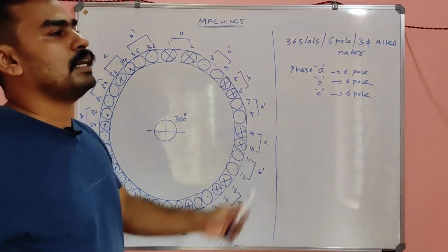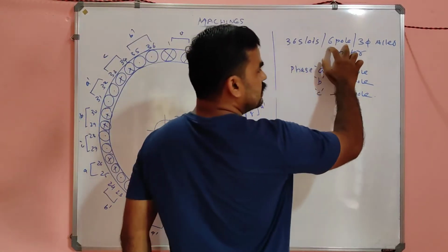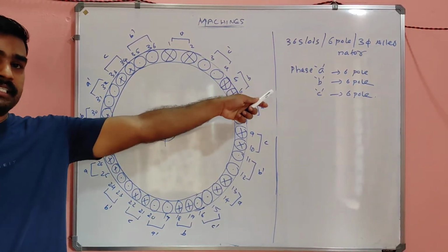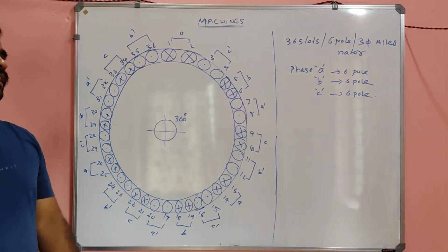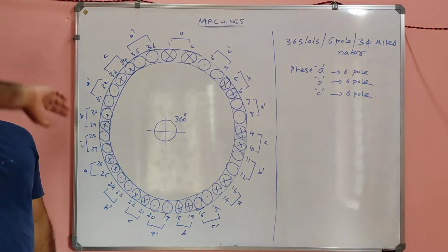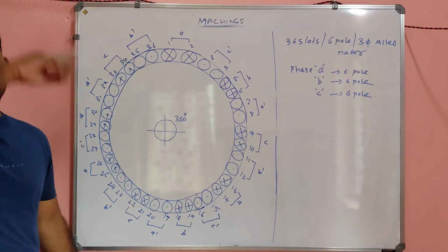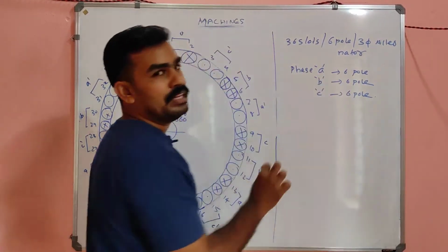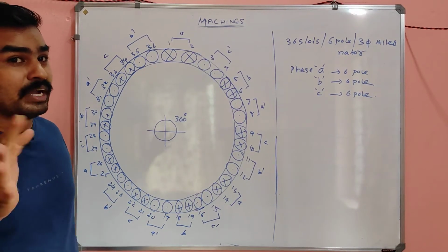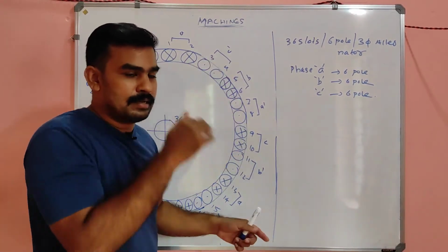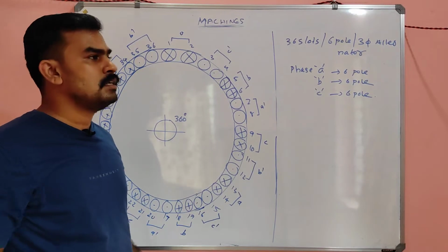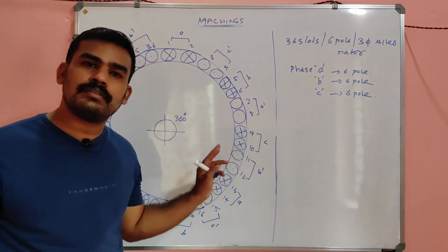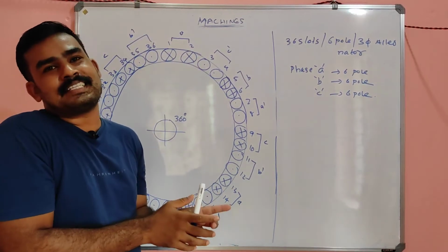But in an AC machine, in winding methodology, poles does not mean the total poles of the machine. It is for the corresponding phases. In the rotor of a salient pole alternator, if you say 4 poles, it is for the whole system.